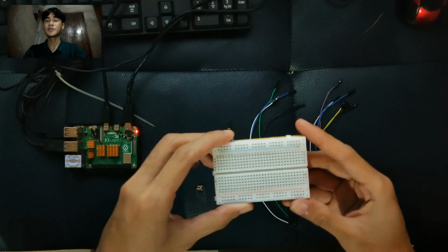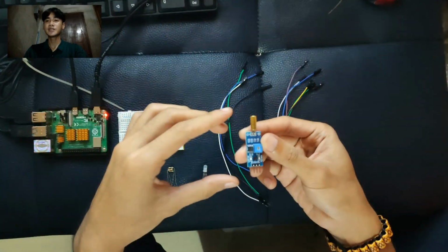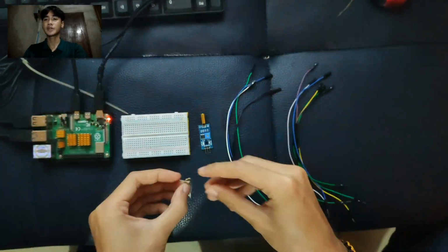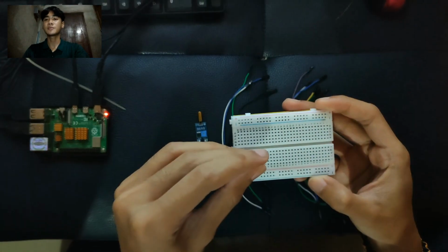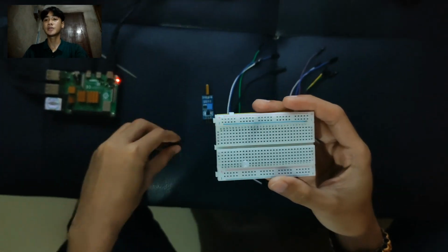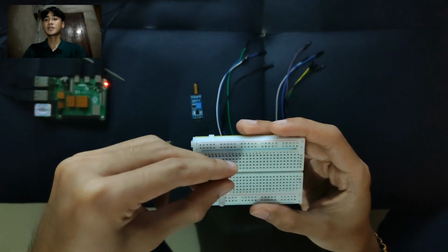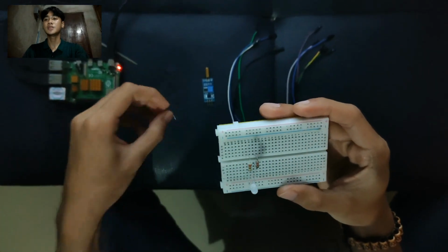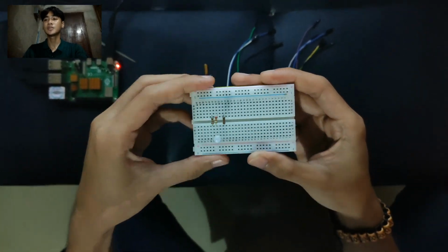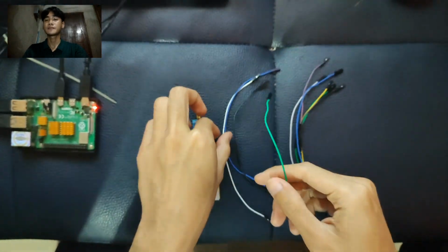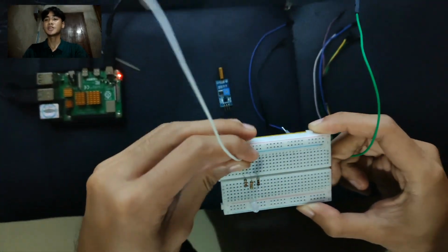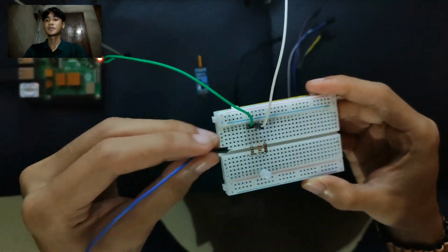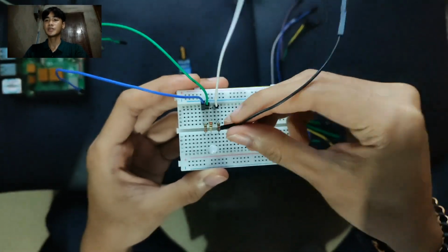For the demonstration, we need a mini breadboard, a tilt sensor, an RGB LED, 220 ohm resistors, and jumper wires. First is to mount the RGB LED pins on the breadboard. Connect the 220 ohm resistor to each of the RGB LED pins, excluding the GND pin. Connect the longest pin, or the GND pin, of the RGB LED. Then connect the tilt sensor with jumper wires.